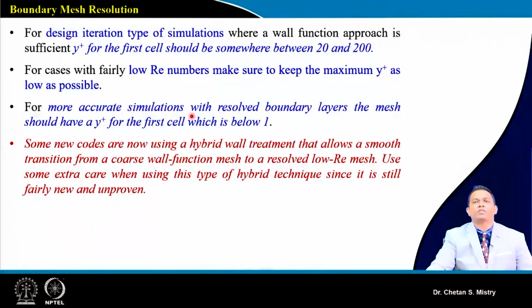There are some commercial calculators available in which you can put your Reynolds number as one of the parameters along with some flow properties. It will give you the calculation of y plus. That y plus value we will be using for making layers near the blade surface.